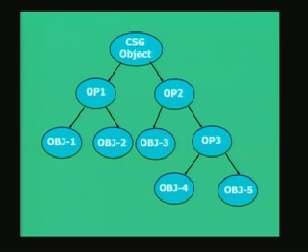And we will say that of course, CSG could be at the root, which will be a resultant of a union of two different objects. That means, at the lowest level I use object 4 and object 5. If you look at the right hand side subtree, at the leaves object 4 and object 5, you use an operator 3 labeled here to create a structure, which is again combined with object 3 at the operator 2 level to create one object. Then you take object 1 and object 2. We of course assume here that object 1, object 2, object 3, object 4 and object 5 are 5 different, or some of them similar type of simple 3-dimensional geometrical primitives, which are used to create complex structures.